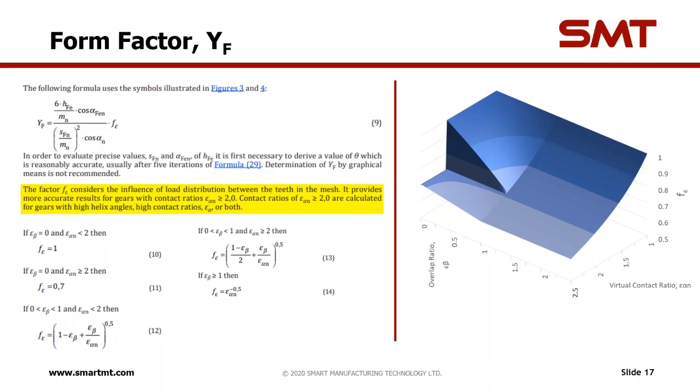One of the things I would like to focus on here is we should be careful with this change, because if we have a spur gear and we think we are just over contact ratio of 2 and we add a tip relief, we might suddenly have a contact ratio less than 2, which might not equate to this difference.